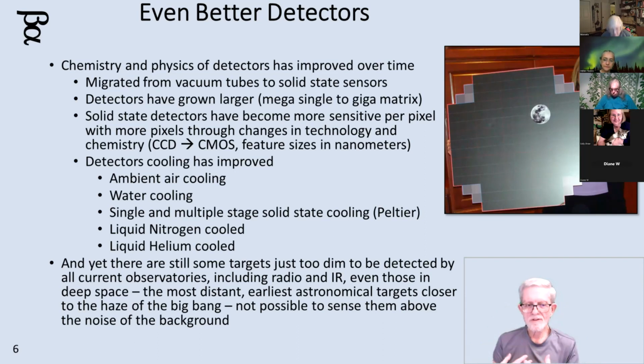We've also changed from just using the chips as they are to putting fans on the chips to cool them down, because the heat of the electronics in the chip actually creates electromagnetic radiation noise in the infrared. So if you're trying to create an infrared detector and your chip is actually producing heat, that will restrict the minimum light level you can see. So we cool the chip.